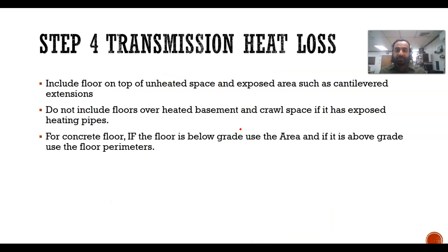Moving on, step 3 is the transmission heat loss, which is a little bit more involved. So the infiltration is one side. You get the volume, not the area. You get the volume, the heat loss factor from the previous slide, and the temperature difference. So include the floor for the transmission. Well, we will lose heat from the wall to the outside, and the ceiling and the floor.